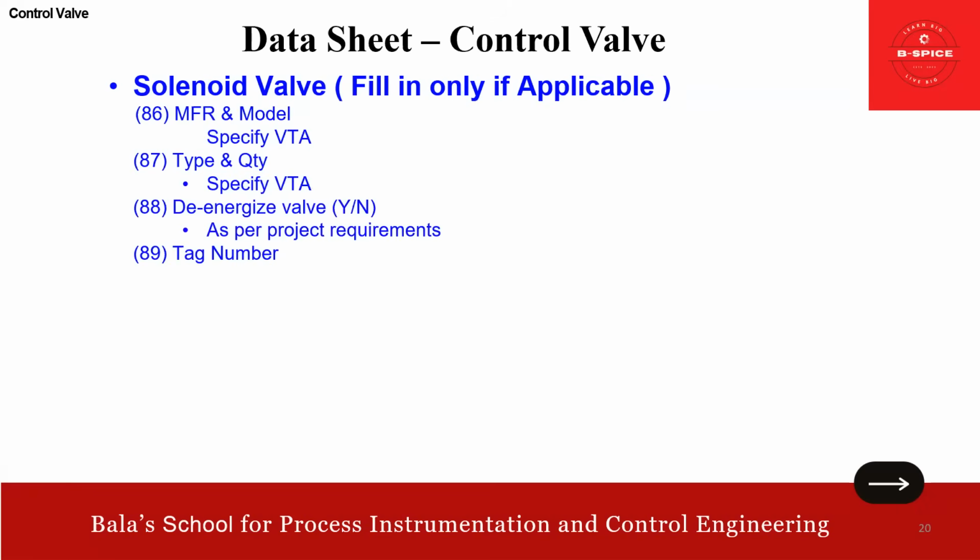Then, yeah. Basically here, the point is to specify valve stroke direction when solenoid is energized. So basically it is recommended to adopt normally energized circuitry unless specifically specified as energized to open or close the valve for special application such as FGS. So this is the point you need to check.